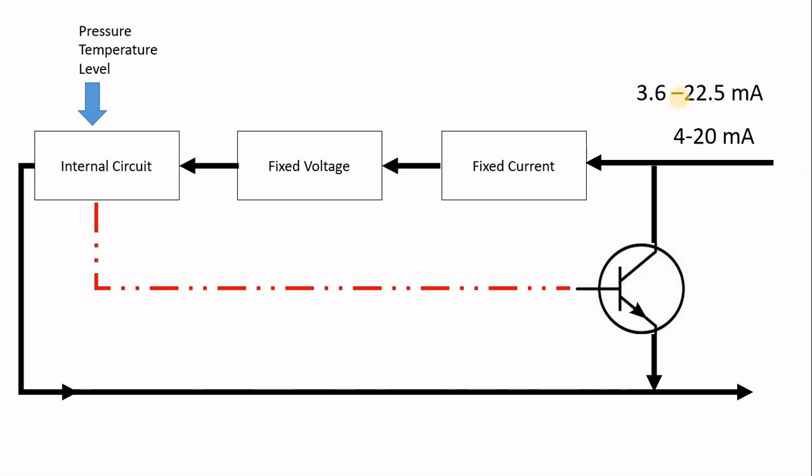Again, some transmitters can be configured to go below 4 or above 20 if there is an internal error in the transmitter. To be able to capture this feature, your card in your PLC or DCS should be able to read outside the 4 to 20 milliamps. Be careful, because most of the cards in the PLC will tell you 4 to 20 milliamps.